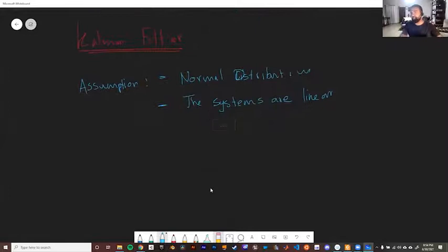And the assumptions are there, as you know, to make things easier, but sometimes those assumptions break down. So you will need to be aware of what the assumptions are, and if something is going wrong, you'll have to try something more advanced, right? Or figure out ways to get around that assumption, which is what the extended Kalman filter does to a certain extent. It deals with this assumption of linearity, but even in that, it assumes that you have a normal or Gaussian distribution. Okay, so good question. Any other questions?